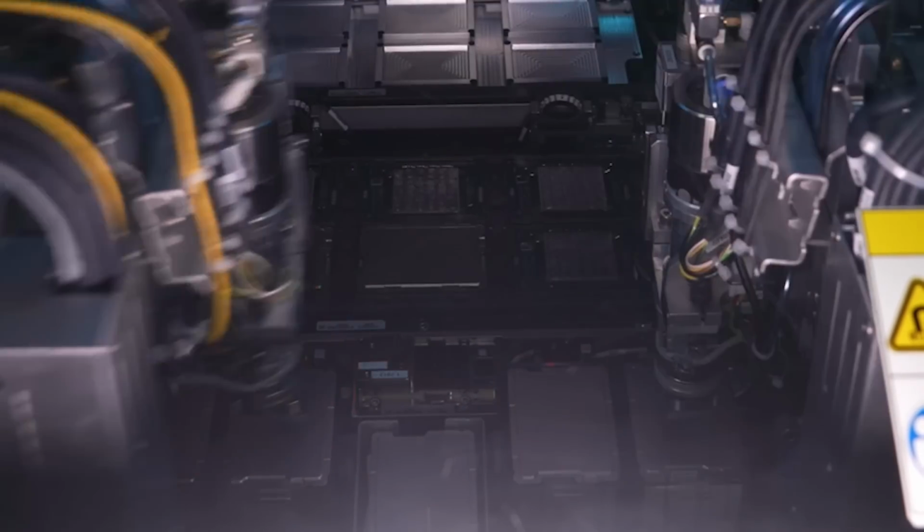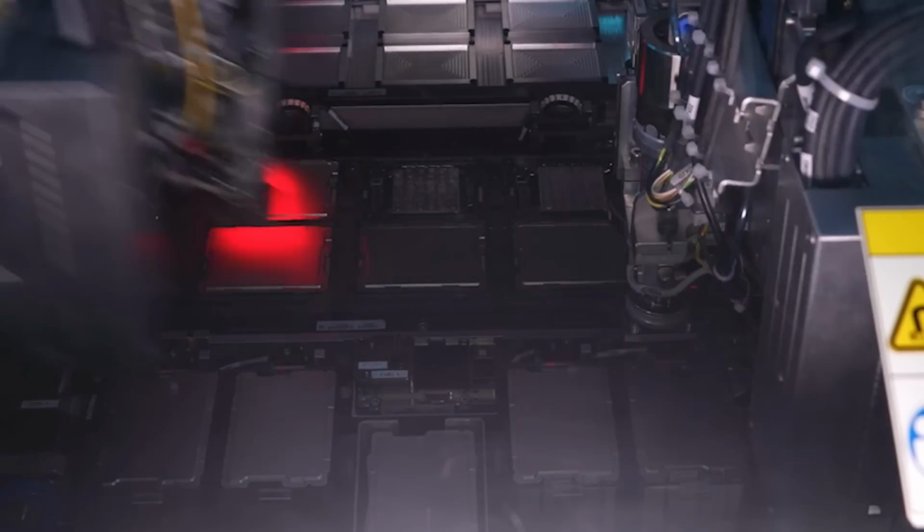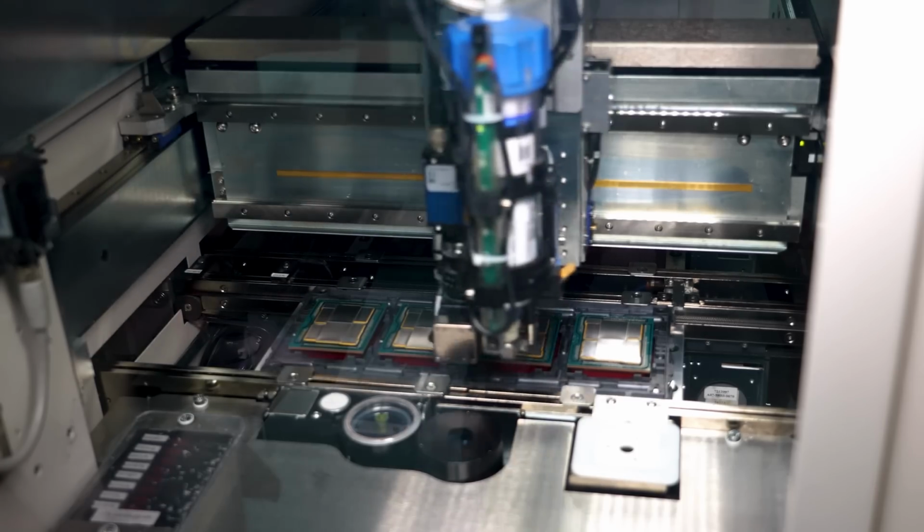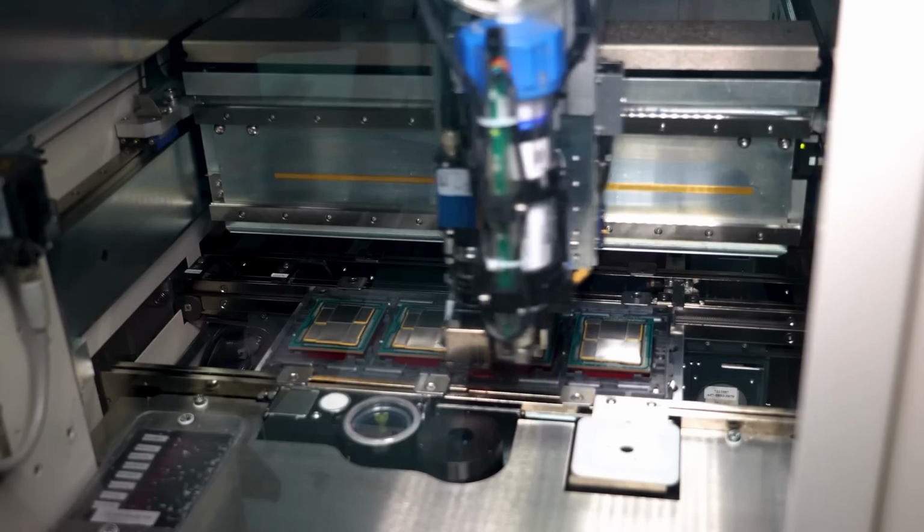We stack all the die onto the wafer, and then take it through the flow. We then singulate or chop up that particular die into what we call the die stacks or the Foveros stacks. After that, circling back to that singulated die test, we do have the option to test them again. Since we are able to test at the die level, we are able to test at the die stack level. I think this is a big advantage.